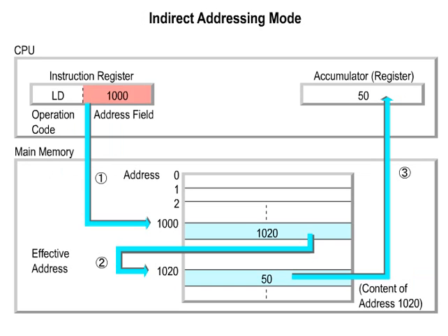In indirect addressing, you can make various changes to the data targeted for processing, by just changing the data specified in the address field, without changing the address field of the instruction. Because of this, it is often used for handing over data between two programs.